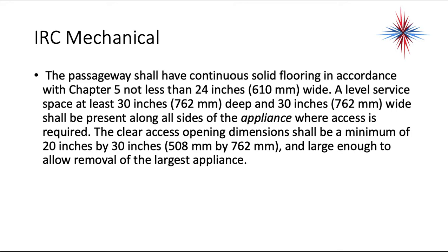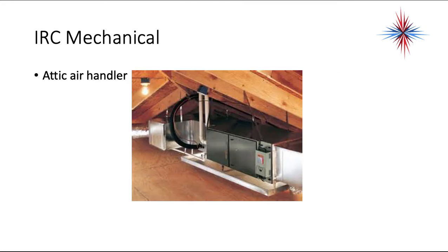Okay? In other words, you don't have to crawl across insulation and beams and open floor areas and take the chance of kicking out a ceiling to get to an attic appliance. There has to be space and a floor for you to walk to that appliance. This is an example of an attic air handler.